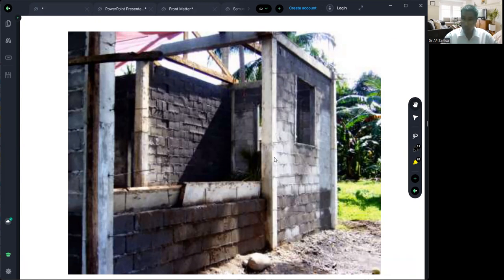Reinforcement meaning, according to the code, the minimum diameter of the deformed bars is 10 mm. I think that is also in the Philippines, but we still use 8 mm. We still use 6 mm. But for connector purposes and for other functions, not as a structural reinforcement.